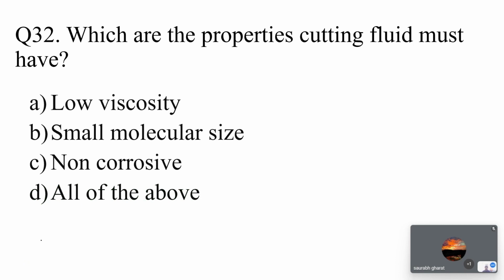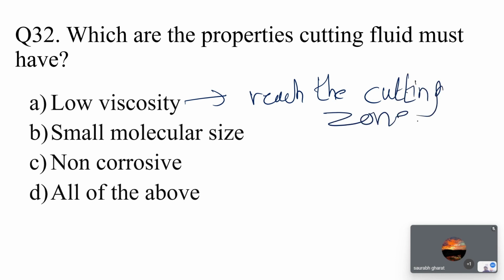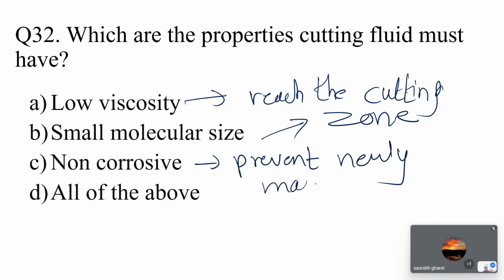Which properties must the cutting fluid have? It needs low viscosity, to reach the cutting zone. It should also be non-corrosive, to prevent corrosion of the newly machined surface.